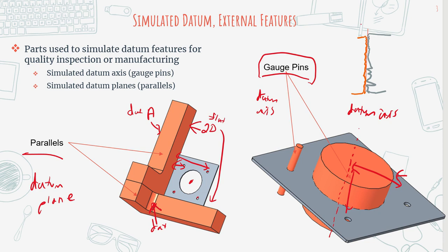So another thing I just wanted to talk about here quickly is, we talked about, for instance, how you have a parallel and you have a plate. So where exactly is the datum, right? So this gives you a better idea of what we're talking about here. You can see that the orange represents the surface of the parallel. And you can see that this surface is finely machined, and there's very little, I'm going to say something like plus minus 0.0001 surface roughness, but the plate itself might be a lot rougher, and this might be something like plus minus 0.05.